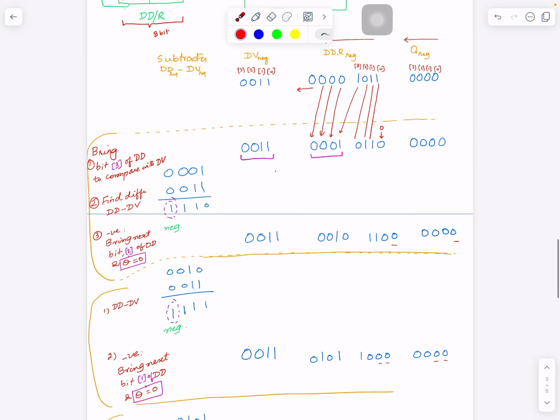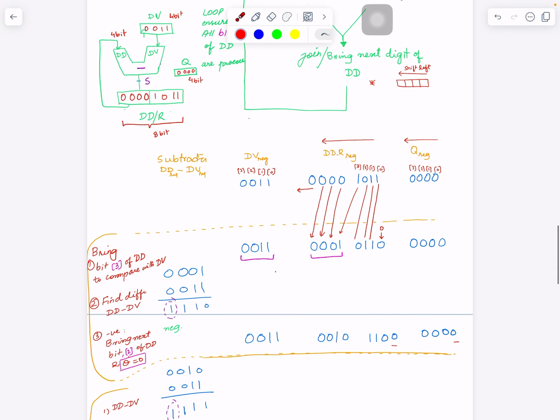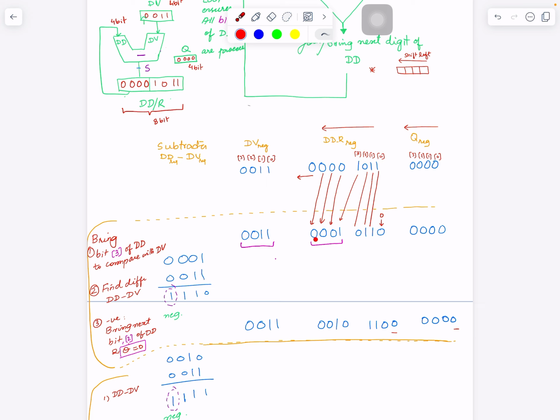So we are doing this division on the side. If you remember, the way we do the division is 0, 0, 0, 1, 0, 0, 1, but I have done this. There are two ways you can think of. Actually, I should tell you the right way so you're not confused. Your top is 0, 0, 1, and the bottom you take the 2's complement of that, which is 1, 1, 0, 0, which is the 1's complement. You flip all the bits, and then you add one, that makes it 1, 1, 0, 1. Then you add them, so it becomes 1, 1, 0, carry 1, 1, 1, which is this.